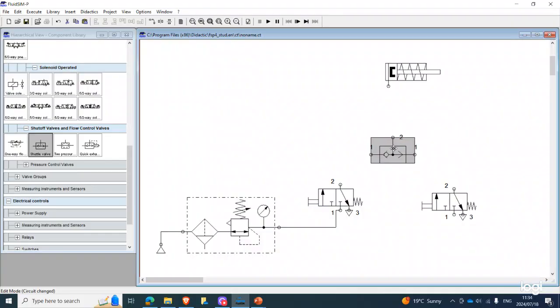So an OR gate allows us to advance the cylinder on either this pattern or this pattern, right? So both of the push buttons don't need to be pressed or activated for the cylinder to advance. Only one of them, since it's an OR condition, so you can control the system from the loading or unloading side. So connect from here to here, right? And then straight into the piston, right?